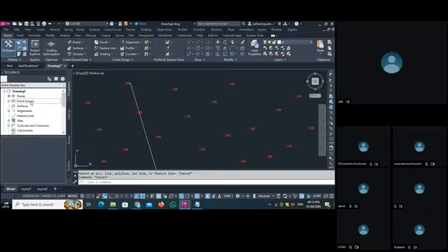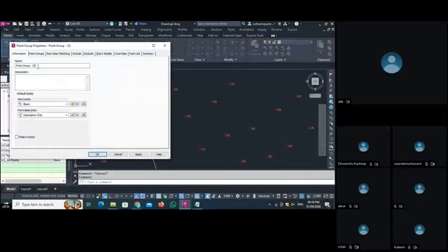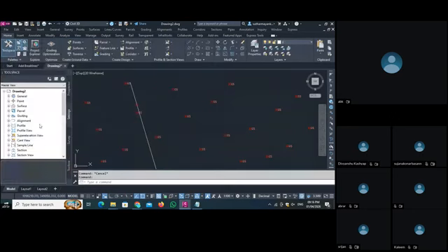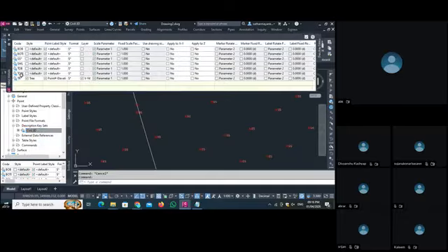When we create a point, if you want to export this point, you have to create one point group with the name bore point. As we don't have any description key here, we go to settings, we go here to point, from the description key set we select this, the edit keys, and click here and click new.